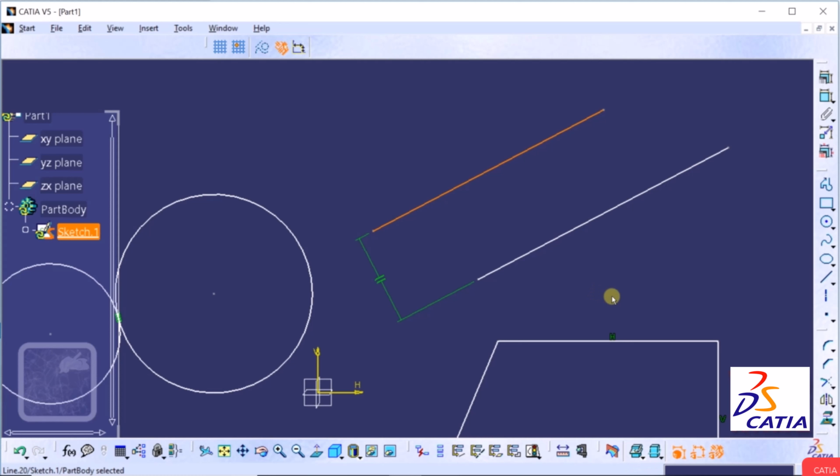Similarly, we can also make lines tangent. We can insert the symmetry by using the automatic constraint. So automatic constraint is really important because it saves our time. Instead of inserting the constraint manually, we can use this automatic option to reduce our time of sketching. So when we cover up some more examples of drawing the sketches, we will learn about these constraints in more depth.